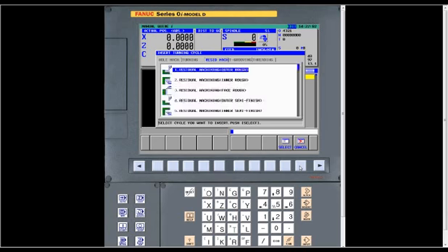And just to give you an explanation of what that is, say, for instance, we're turning a part that has a large relief that only one particular type of tool will fit into. What the software does, as long as you have your tools described right, it'll look and see if a tool has clearance to get into that relief. If it doesn't, it'll give you a little message saying residual stock will remain.